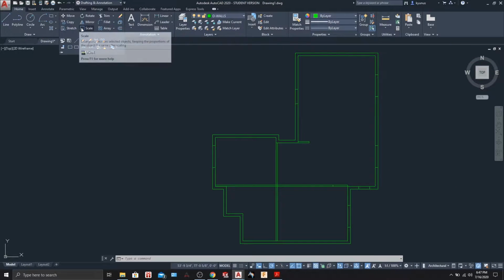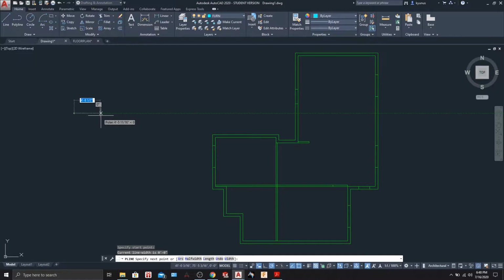Let's talk about move and copy. Let's quickly draw a dining table so we can keep it in our living room area. We have a dining space over here, so we will keep it over here itself. For that you can either use line, polyline or anything. Let's go for polyline. Let's start from here, go for 3 feet, come down 4 feet, then we can snap the endpoint and press enter to finish. Right, single entity, nothing complicated. We have our dining table.